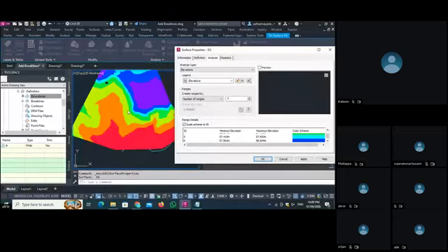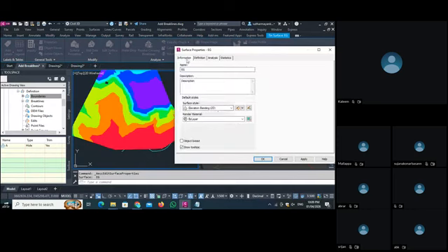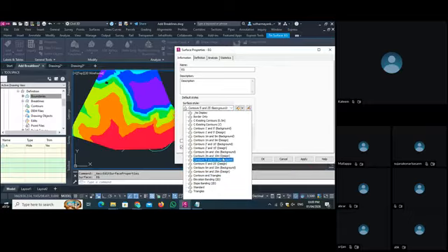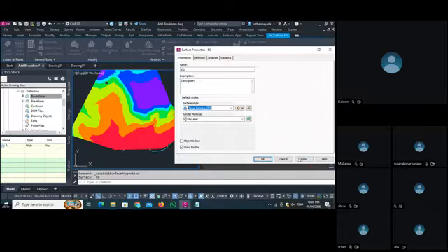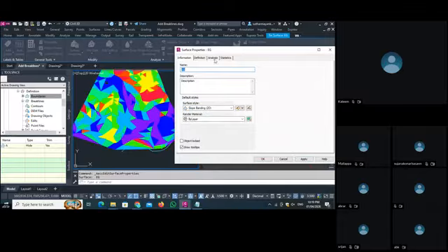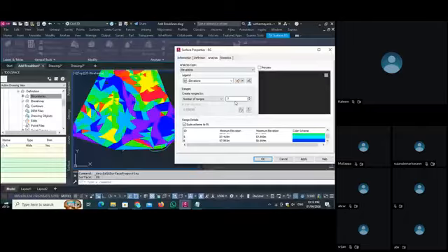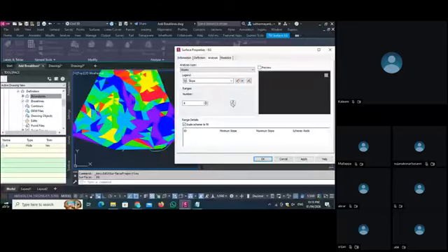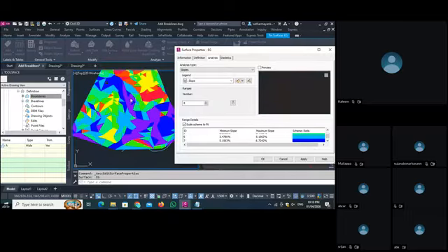So this is one way we analyze these things. Now in the style, let's select the slope banding, apply. The same way, if we go in analysis, you can set your slope from here. Again, you can click on run analysis. You can put the minimum and maximum slope. You can change your color from here, and you can analyze your surface from here.